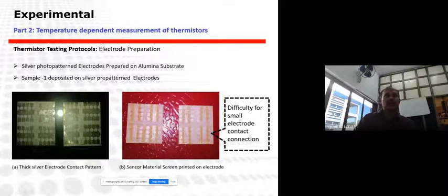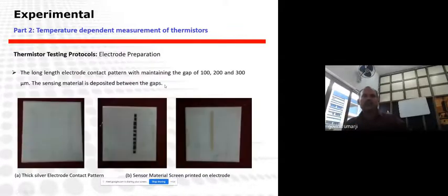On the aluminum substrate, what we observed is that we had difficulty measuring the contact, because the contacts are very near. We thought that we should first make a small device, but the initial attempt went wrong. So we redesigned our pattern, with elongated contact lengths and contact pads,